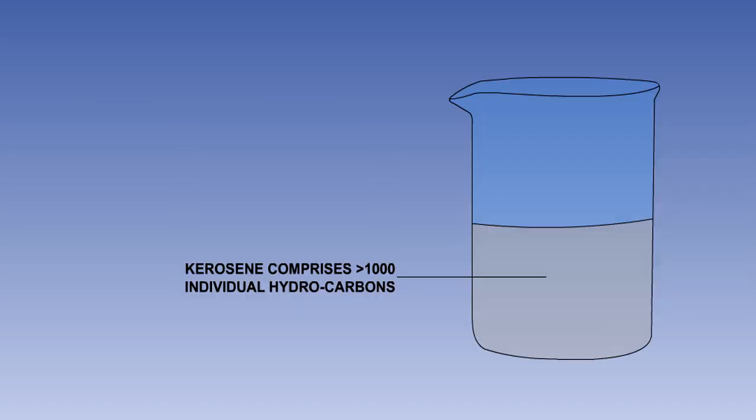We are now going to talk about fuel waxing. This is something that happens to fuel when it is extremely cold. Do not confuse this with the water in the fuel freezing. Gas turbine fuel consists of many hydrocarbons, each with its own freezing point, so it doesn't become a solid at one temperature in the same way that water does.